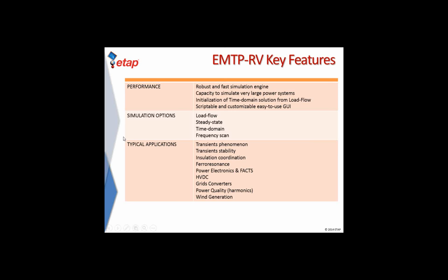We do have four simulation options in the software. As I said, load flow and steady state. The main simulation option is the time domain analysis to simulate the transients. And we also have a frequency scan. Frequency scan can be used to check if you have any resonance in your system or to design harmonic filters.